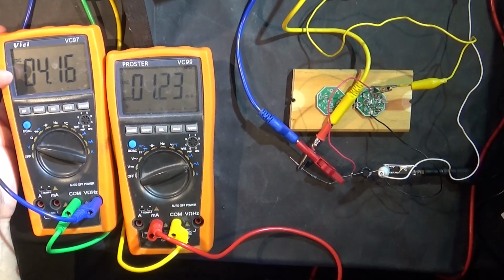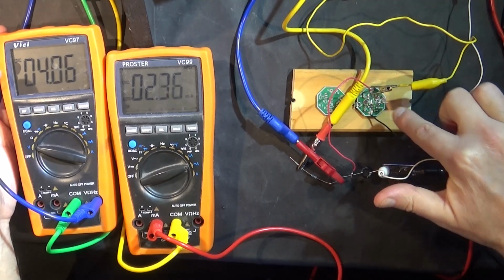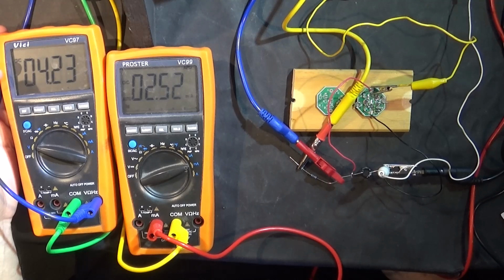Oh, there it is, 7.9 volts. It'll just about creep up to the trigger voltage. And we said the circuit was going to run at 12 volts. So let's wind it all the way up to 12 volts. And yep, she's blinking nicely.